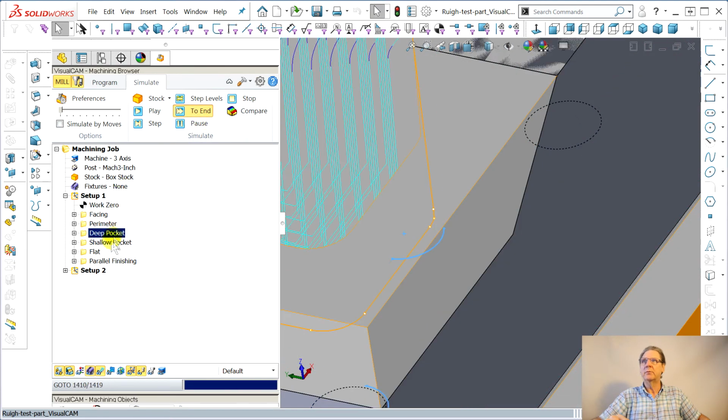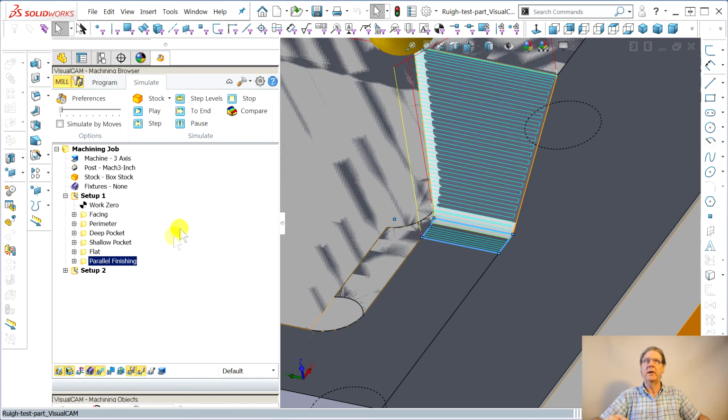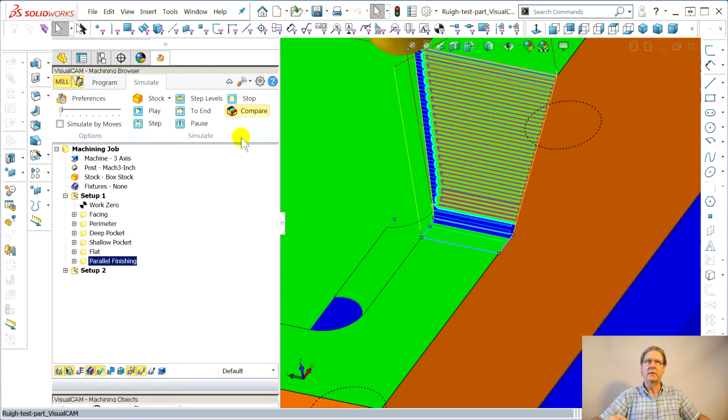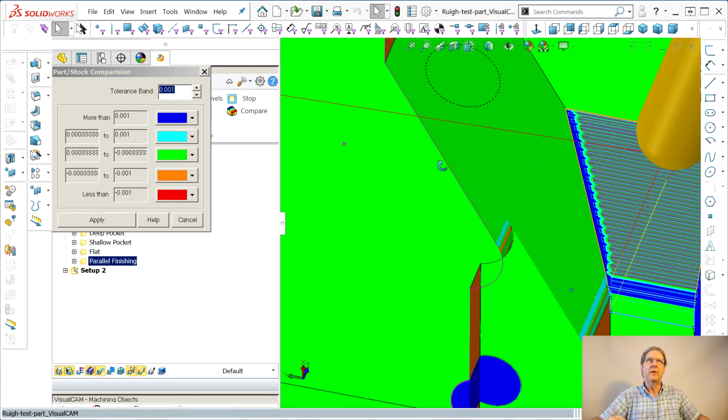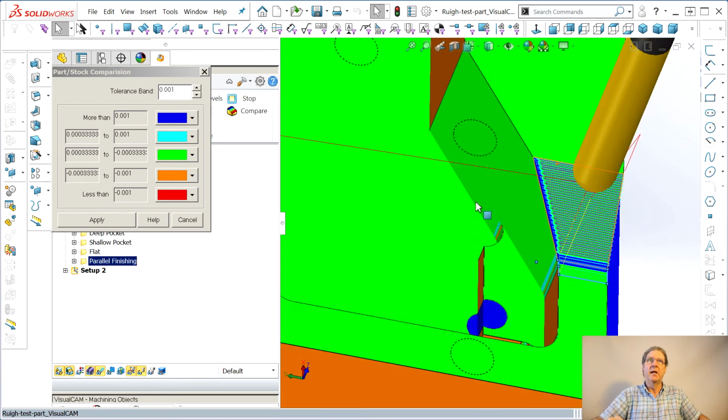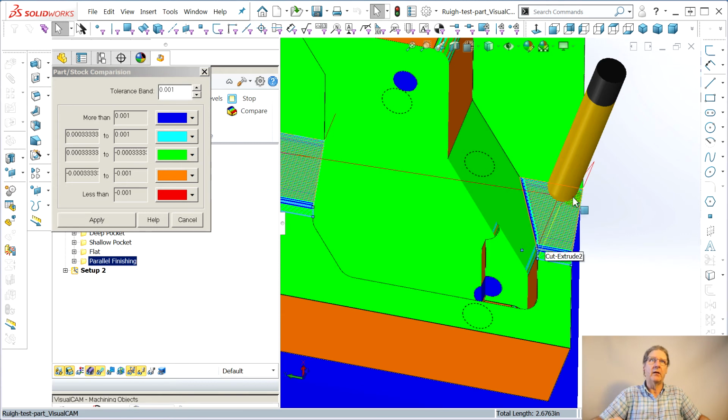It's thinking, it's doing the perimeter, it's doing the pocket, it's doing flat, doing a parallel finishing. Compare. See? Now with SolidWorks CAM, and this is because Dave's a genius, and he knew that putting this angle on this area, that pulls up. SolidWorks CAM, same as CamWorks, they let you define the radius. They do all this Z. They want to come down and, like a bathtub, do it like that. These guys are much more efficient. They get down, they stay down, life is good.